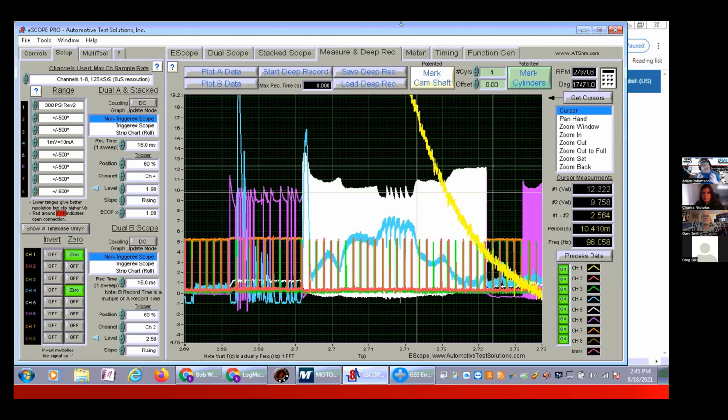Instead of, which would have been neat, the computer going, hey, by the way, we had an under voltage situation. We went into chip protection. We tried it 5 times, couldn't recover. We shut it down. Right. That's pretty neat, because the codes alone and the troubleshoot code charts can be so misleading because they are not going to show you this. You know what the code was? The code was motor mechanically faulty. And it was reading that because of this, but it never identified whether it was overcurrent, or under voltage.